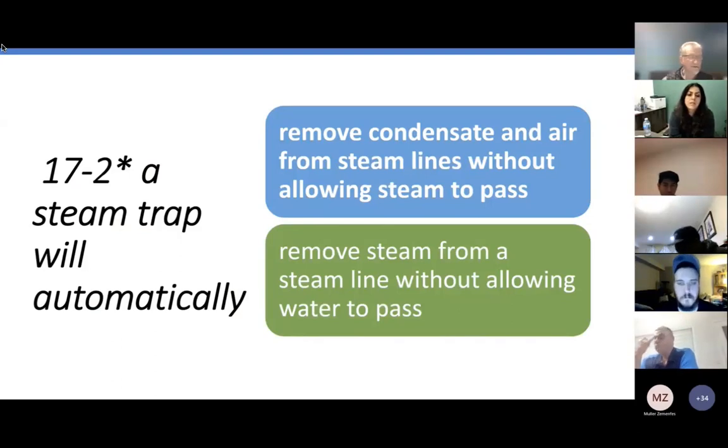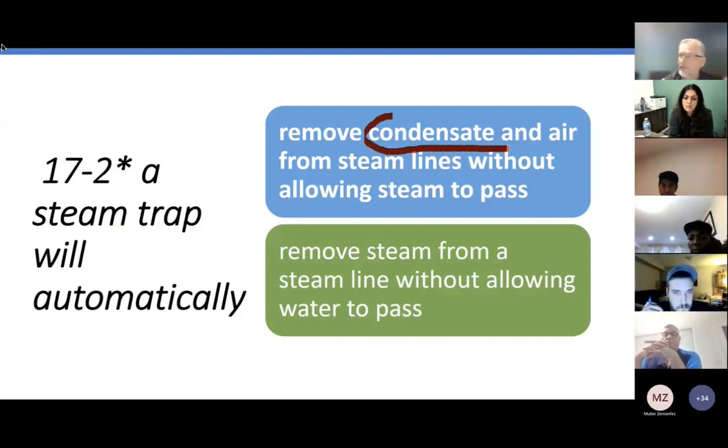Those of you that saw the first water hammer video we showed just a few minutes before 6, they talked about 50 G and 3.5 tons on a small little 2-inch valve disc. So tremendous forces can be caused by not removing condensate from steam lines.